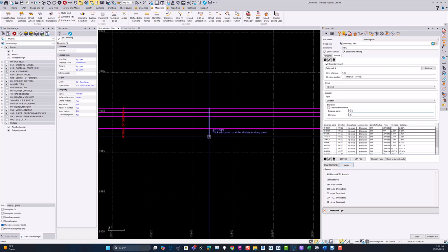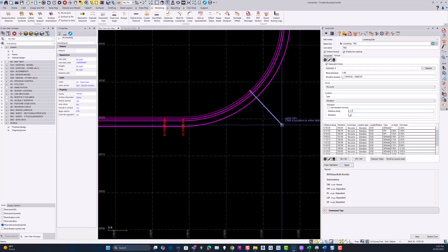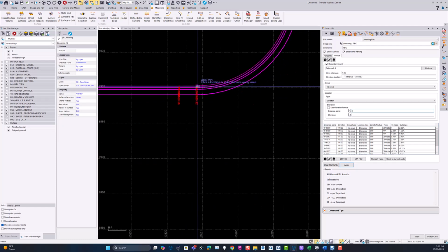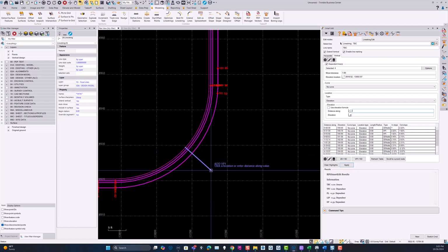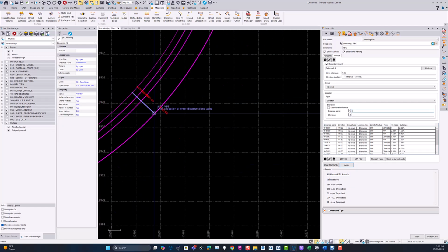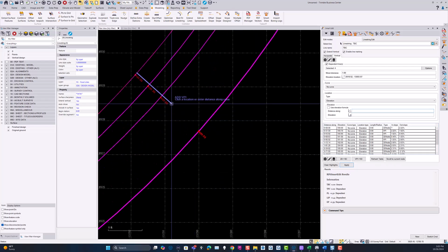If you now go into another point here, and let's say I click here, and let's do this one as 100.9, again I've added the elevations into those. Now that's adding elevations. If I come into a curve, I can put in this elevation right here is at 101, and so if I come up here and want to put an elevation in somewhere along this line, I can say that elevation there is, let's say, 101.5, and that will put elevations and breaks into each of these curves. So now these curves are now split into two elevation locations, so we've got elevations across these lines here.